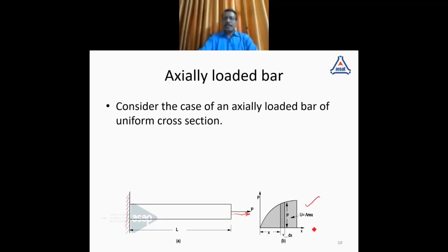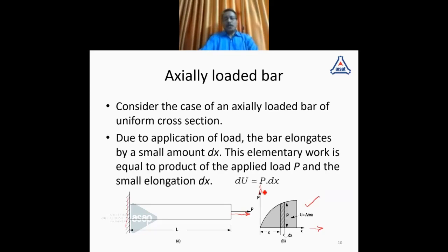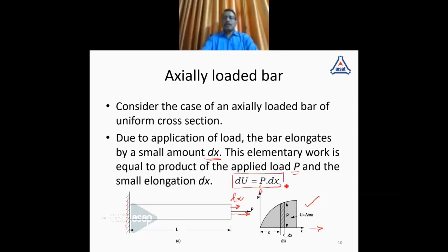The deflection or deformation is shown along the x-axis, and load is shown along the y-axis. When you represent it like this, the deformation due to the application of load is, let it be dx. When the length is elongated by dx due to the load P, we can say dU equal to P into dx. And this is evident from this diagram also.